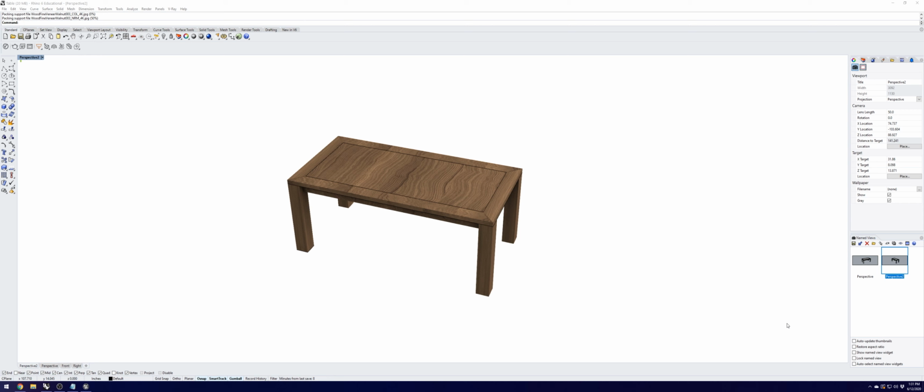The workflow going from Rhino to Unreal isn't as straightforward as you'd think it might be. Many other applications like SketchUp, 3ds Max, and Revit have their dedicated Datasmith plugin that allows you to export from those particular applications into a Datasmith file format that then is imported into Unreal Engine. We're going to do a little bit different for Rhino, but it'll still allow you to get your model in cleanly with all of its UV mapping and textures preserved.